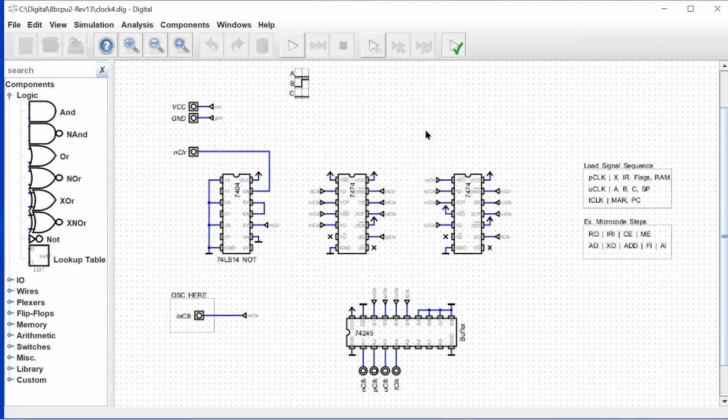So I changed this all over to use tunnels rather than traces, just because I started to do the circuit layout, and it's easy to get confused with the trace lines that we had, because there were a lot of them and crisscrossing. So it's just easier to use the tunnels and validate that the wiring is done correctly when you have a lot of tracks. So that's what I did here. And I also did it so that I could validate in the simulator that the computer still runs and that the tunnels were done correctly. So that was my first step, was to update that.